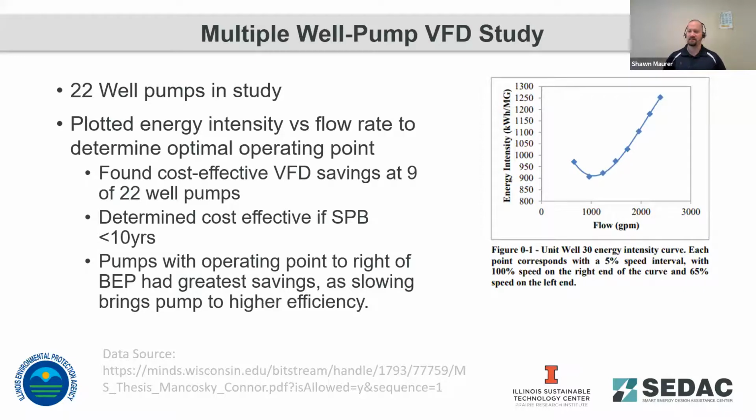And part of CDAC's assessment, if we come out to your site, we can try to get the pump curves for your system. We can do a quick analysis to figure out an estimate of what your system curve is, and we can help you figure out whether a VFD is going to be applicable to your system or not.